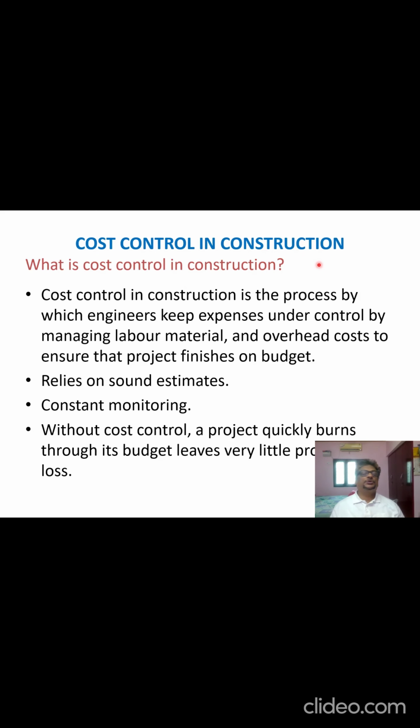So again, what is cost control in construction? It is basically keeping the project under control by managing labor, material, and overhead costs, so that it finishes within the budget and timelines. Cost control relies on sound estimates. Before we start, we need to have the budget and estimate so it can be constantly monitored. Without cost control, a project quickly burns through its budget and leaves very little profit or even a loss. That is why you need to have cost control in place.